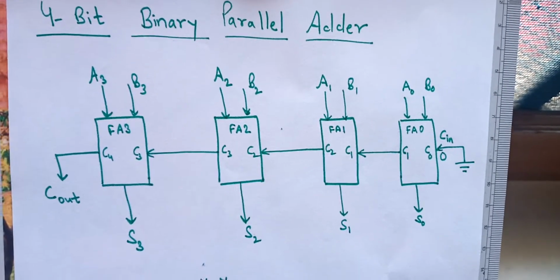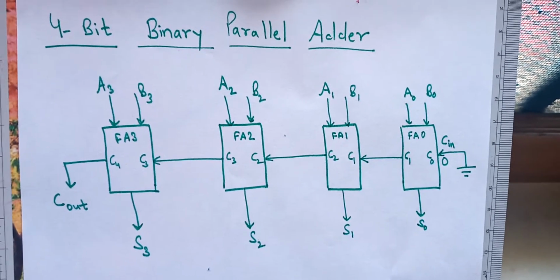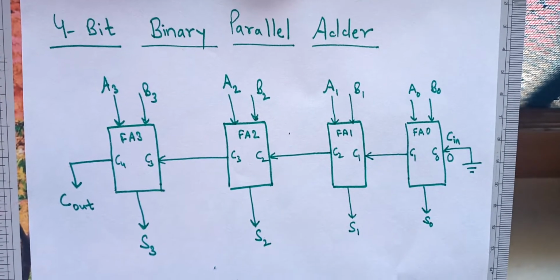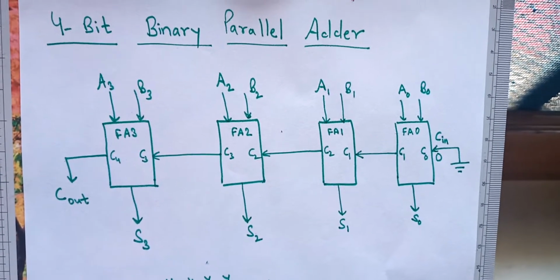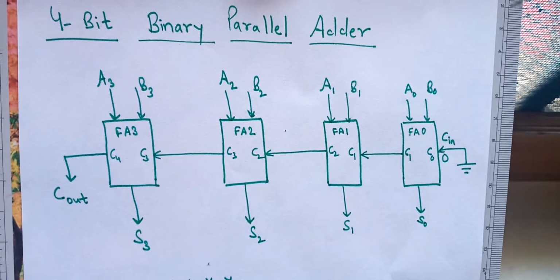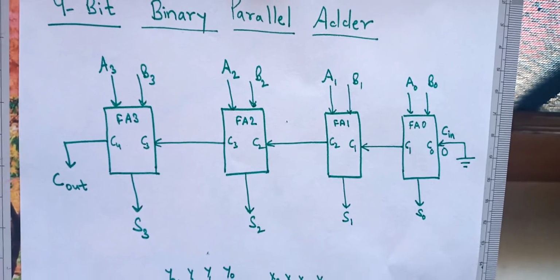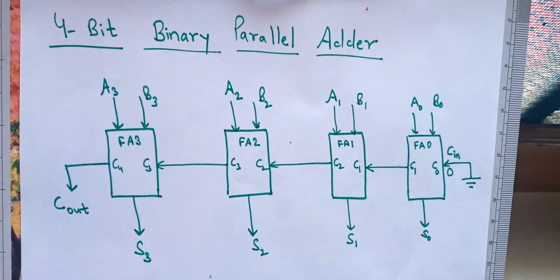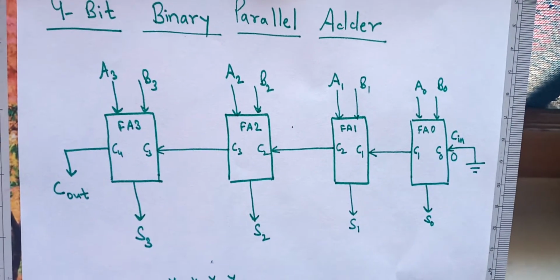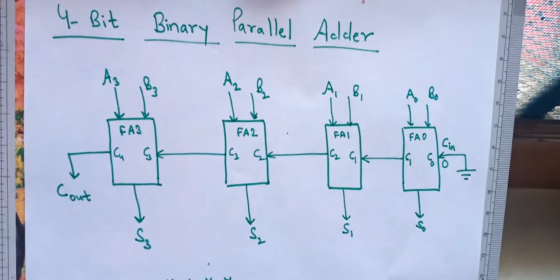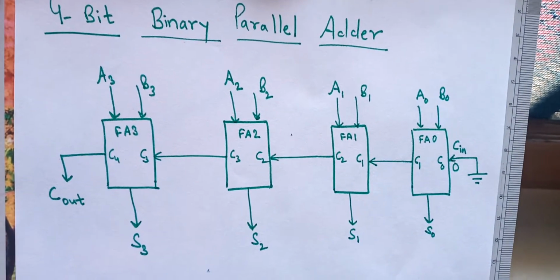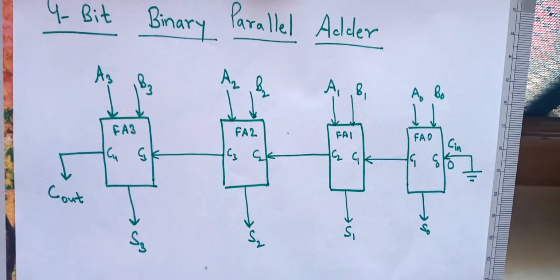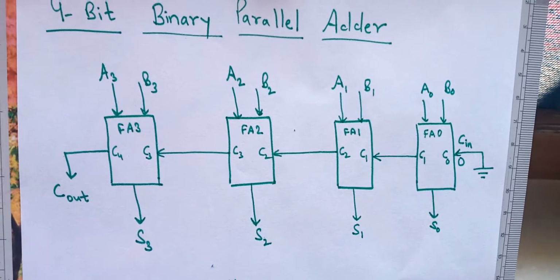You can add any two 4-bit numbers, take a few examples, and check whether Cout is 0 or 1. In some cases you will find Cout 0, in other cases you will find Cout 1, and nothing else other than 0 or 1. So I think it is clear that if Cout is 0, there is no carry generated, and if Cout is 1, the carry is generated.